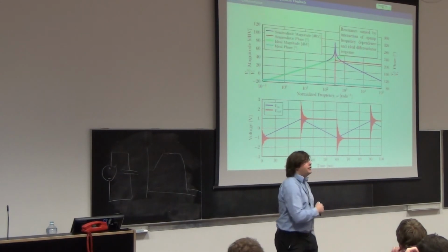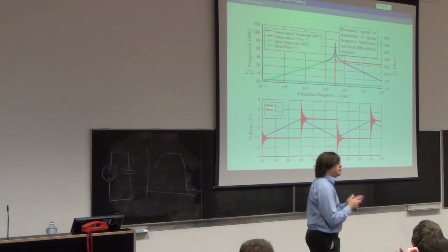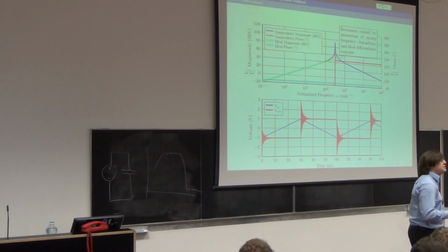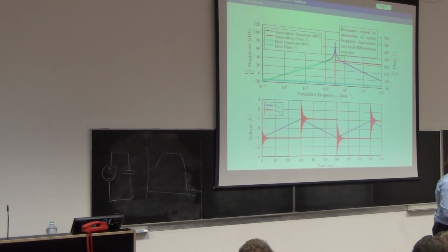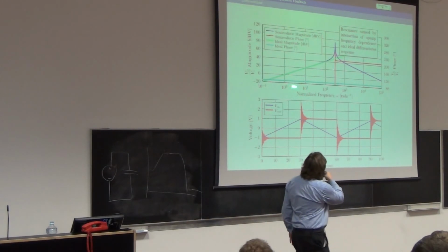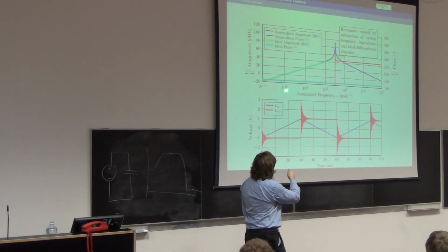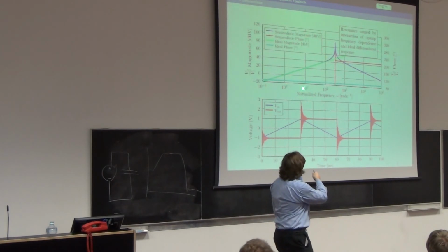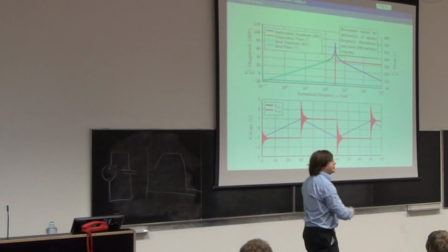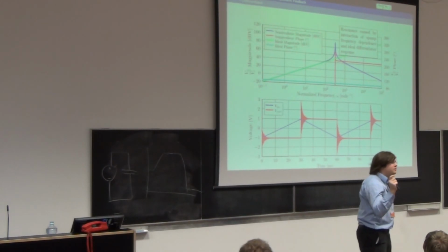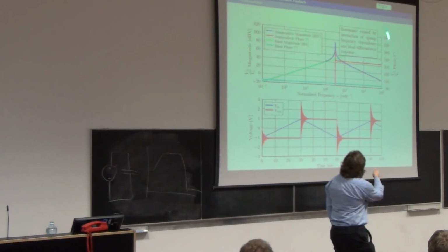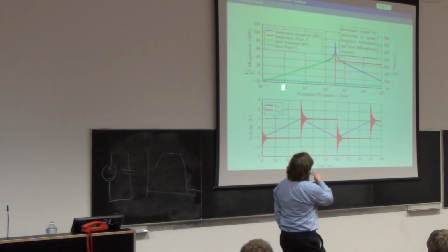And the amount of noise you can get out of a particular bandwidth is essentially constant. It's proportional to something through Kelvin. We'll come to it in a bit. I've got more frequencies in this chunk than in this chunk, because in this chunk there is only 1 hertz worth. Sorry, 9 hertz worth, 10 minus 1. So there's a lot more frequencies up here, and each little quantum of frequency gives me a set amount of noise. So this circuit is noisy up here and not so noisy down here.